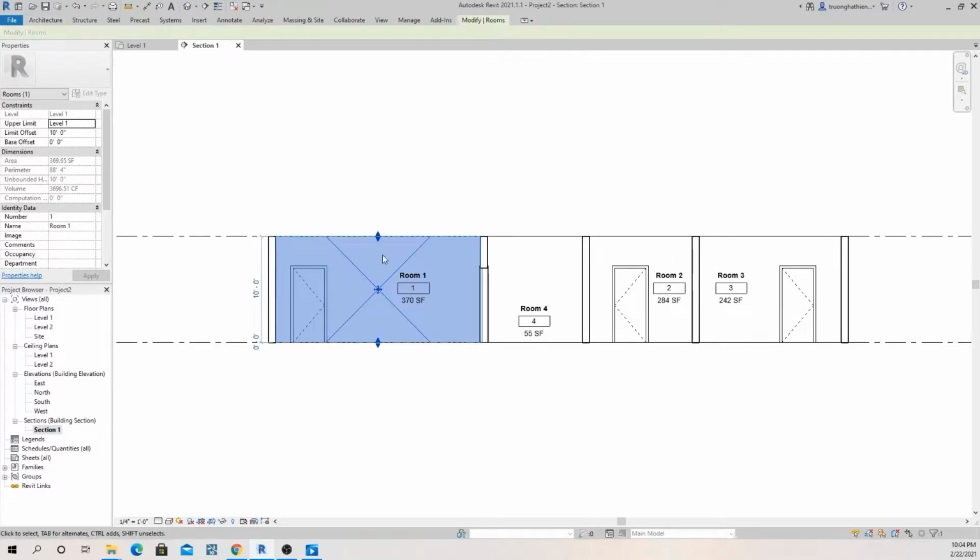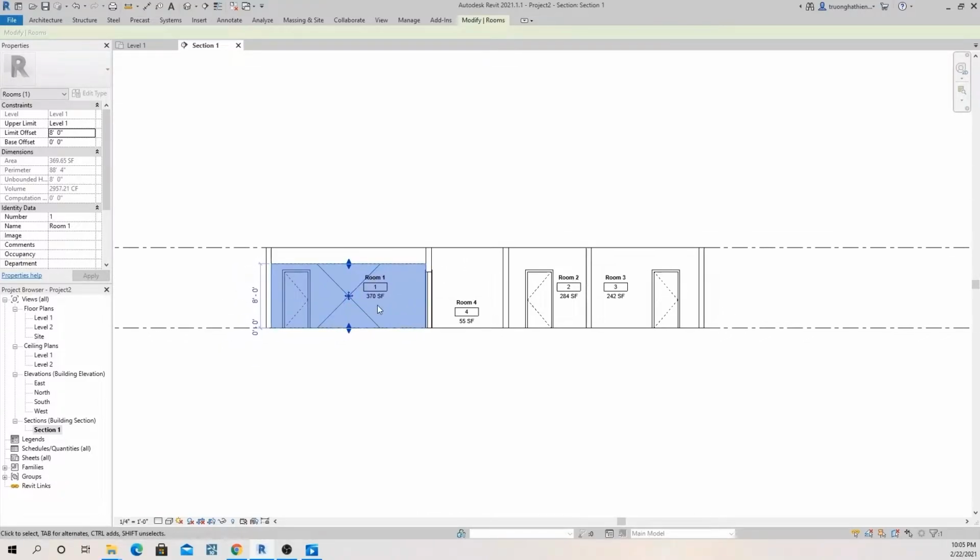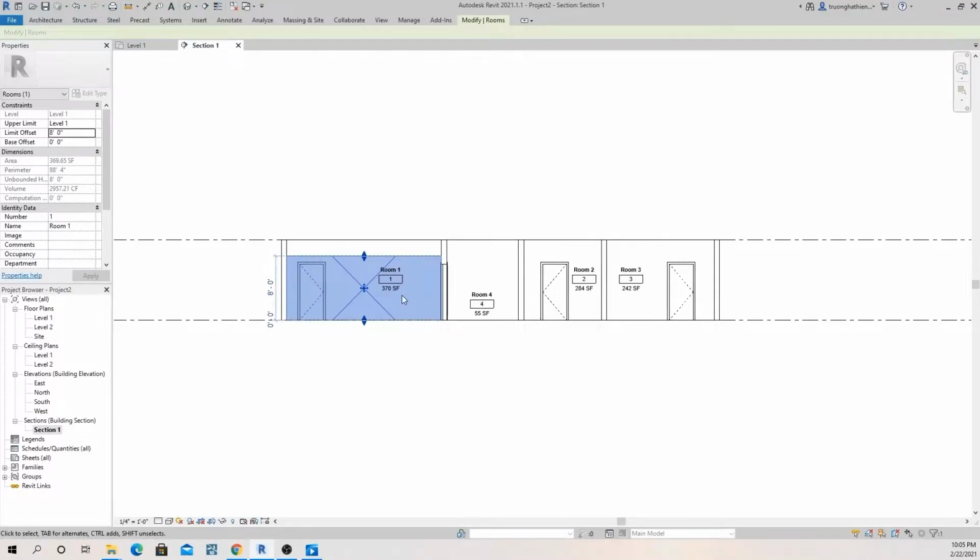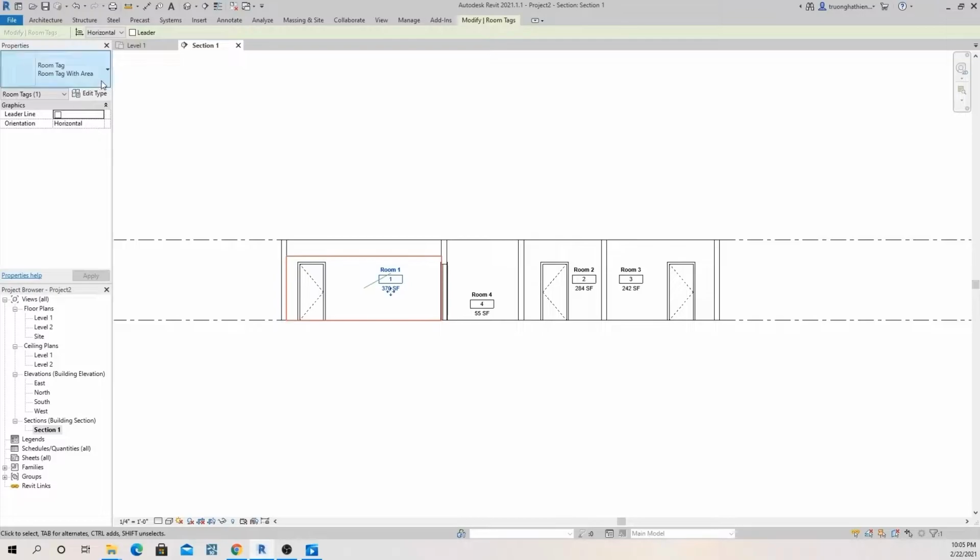And now, like on the floor plan, you can move the cursor to the cross line that appears, and you can see the limits set. That means the height of the space you did define. You can edit that lower or higher, depending on the case. If you have the ceiling, the space needs to be defined exactly from the floor to the ceiling.